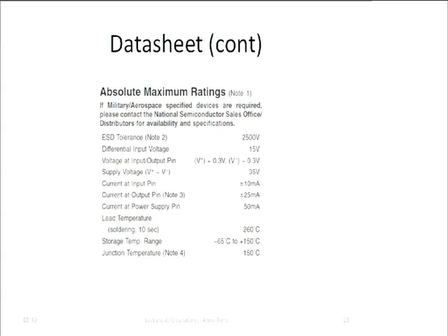We have the maximum supply voltage of this part is 35 volts, and there are a bunch of other things. This can get pretty hot, right? When you solder it, it can temporarily get 260 degrees Celsius. You can use it up to 150 degrees Celsius, but that is inside the operational amplifier. On the outside, it usually has to be cooler, otherwise the heat doesn't get out.